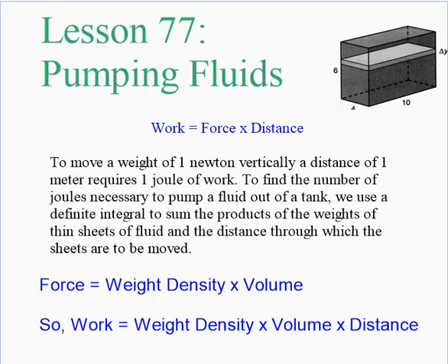The more volume, obviously the more force. So work is weight density times volume times distance, and we'll use the definite integral to sum up the weight density times volume times distance of all these very thin sheets of liquid that we need to pump out.